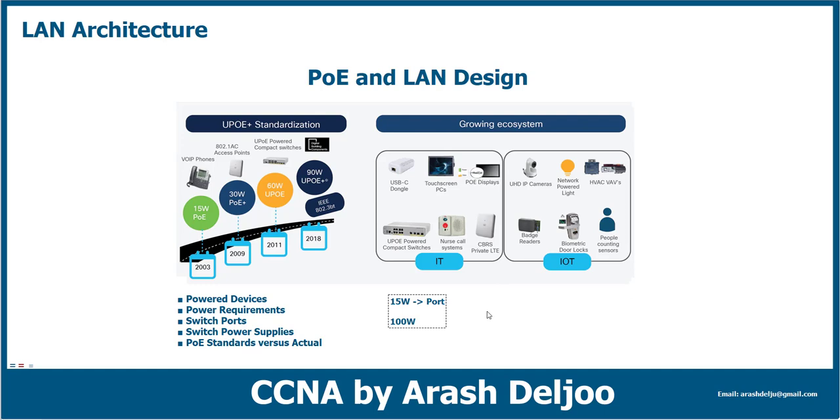Because of that, you should consider the total PoE, or Power over Ethernet, requirement, and after that you should choose the switch with compatibility for the total PoE requirement that you have. Because of that, you need to first identify the devices, or the PD devices, that you have in your network and the number of those devices, okay, and finally you can choose a switch that can provide the power of those devices in each port, and after that the total power of